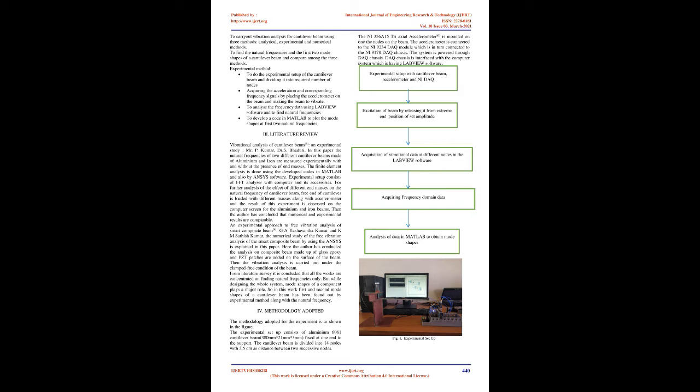Various theories have been proposed, such as Euler-Bernoulli's beam theory and Timoshenko theory. Also, various software such as ANSYS and HyperWorks have been developed to carry out the modal analysis. The values of natural frequencies obtained from these methods cannot be taken for practical design because the theories proposed contain a lot of assumptions that are hard to realize. The numerical methods use truncated partial differential equations, which results in adding a lot of errors. So, finding the natural frequencies from experimental methods is very important, and it is an emerging area in modal analysis.